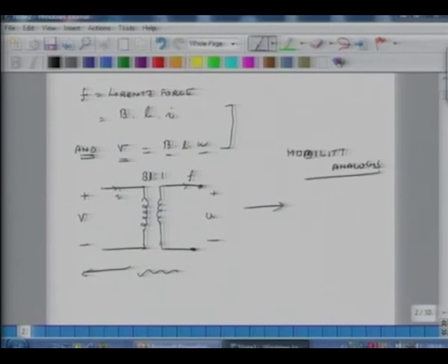If I have the impedance analogy, then I have the same equivalence, but my turn ratio will become 1:BL. You can do the math. Also in that situation, my voltage will be the through variable and my current will be the across variable.